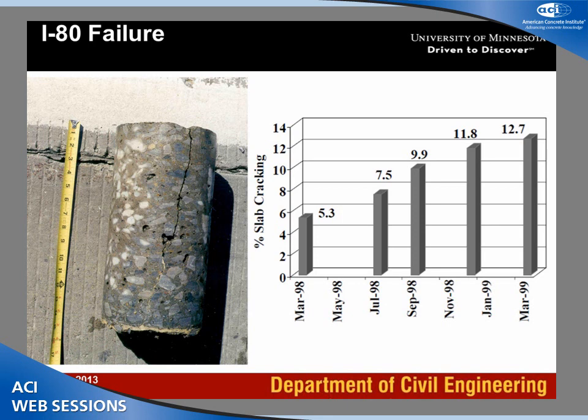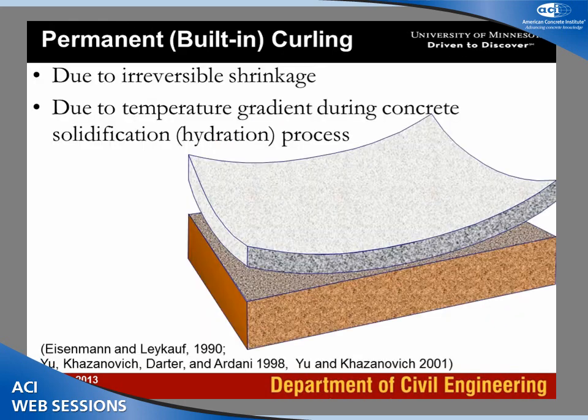At that time, we had just finished development of iSlab 2000, and we decided to simulate various loading conditions. And again, as always, it's easy to explain 50% of the data. We could explain why this pavement failed, but we couldn't this time explain why the adjacent slabs didn't fail. But the most difficult part was explaining why it cracked from the top. And we had to eliminate another implicit assumption of the Westergaard theory.